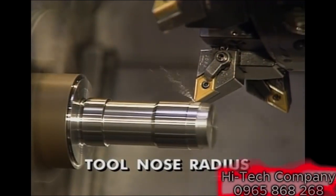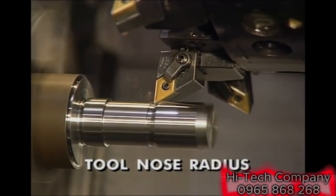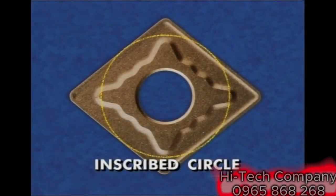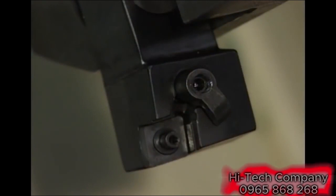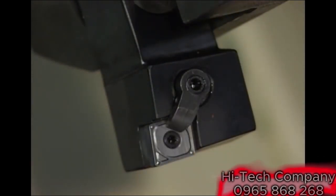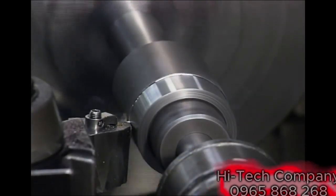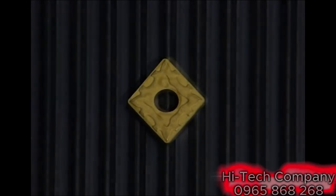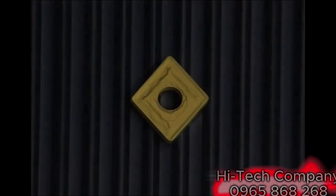The tool nose radius helps determine insert strength as well as workpiece surface finish. Insert size is designated by its inscribed circle, and the inscribed circle size of the insert must match the pocket size of the tool holder. In turning, making a chip is only half the battle. The other half is effectively breaking the chip with the right chip breakers and operating parameters.